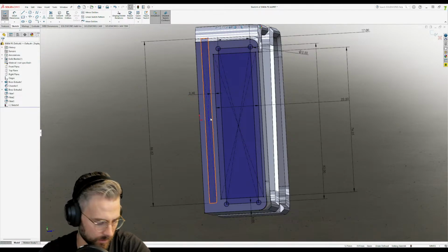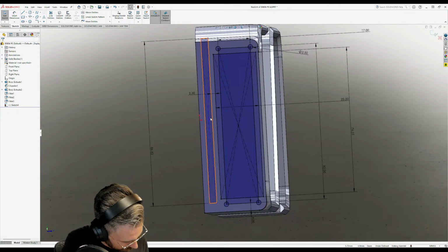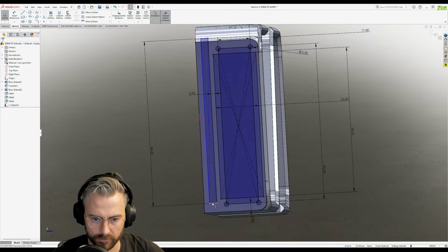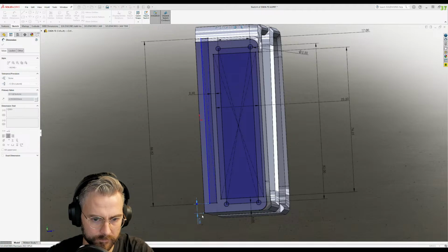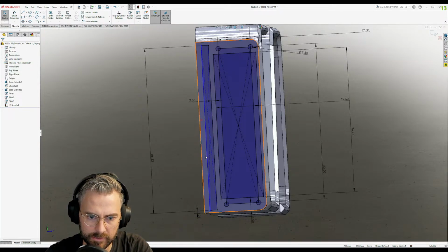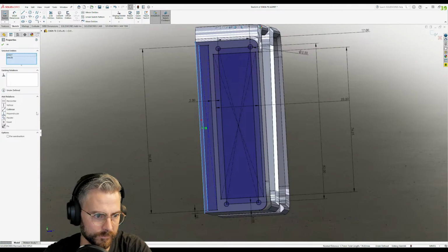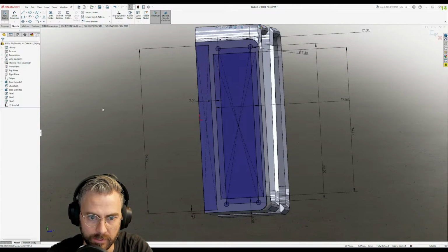But this here, I believe, oh, there's a little gap at the bottom, which tells me how far off the very bottom it goes, and that is 1.25 mil. So this sits 1.25 mil off of here. Smart dimension, 1.25 mil off of here. And this is right on that, so that would be collinear. Collinear says that this line is right on top of that line. So they are collinear. Boom.